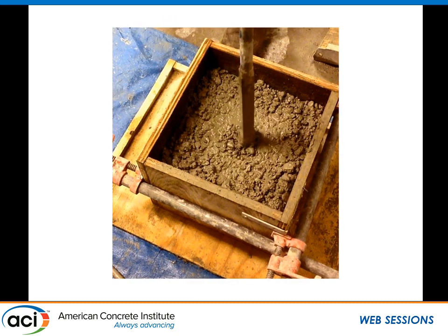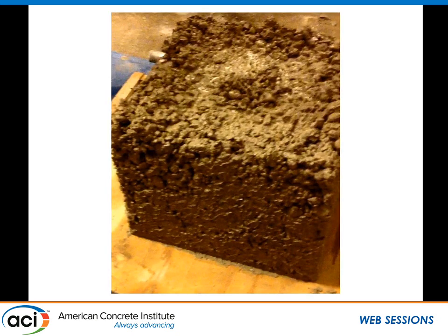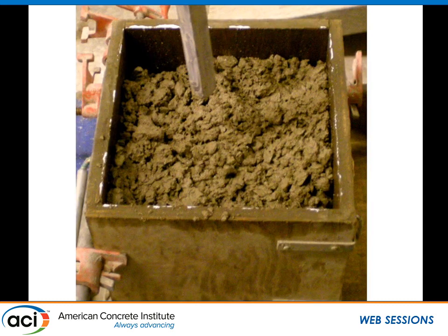But we go down and we go out. We see it's still not getting to the edges. We actually take it out. We actually take the edges off, and look at that. That's not good. Honeycombing. That means that concrete did not respond well to vibration. That mortar did not fill. That's not a good mixture. Okay? Let's look at another one.